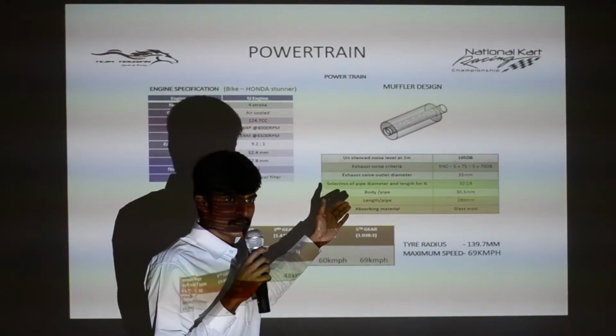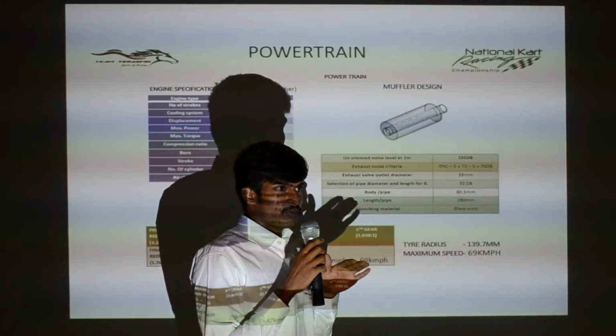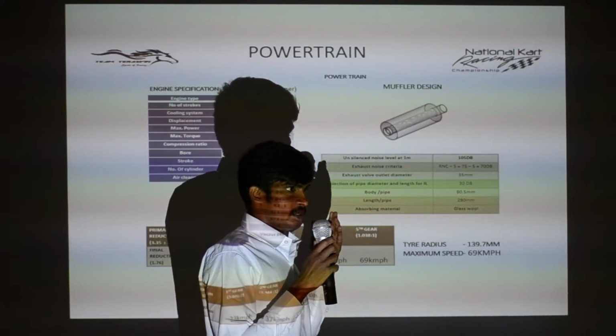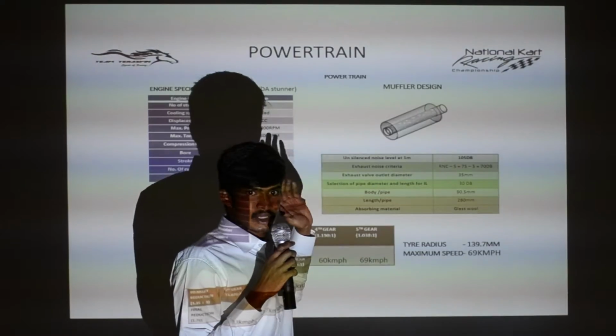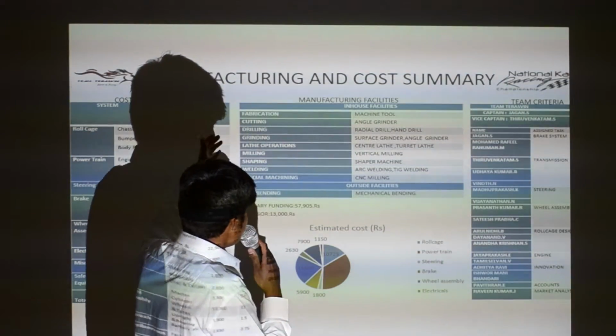And this type of muffler helps in reduction of back pressure when compared with the reactive type, and it increases the performance of our engine. This is our manufacturing and cost summary.